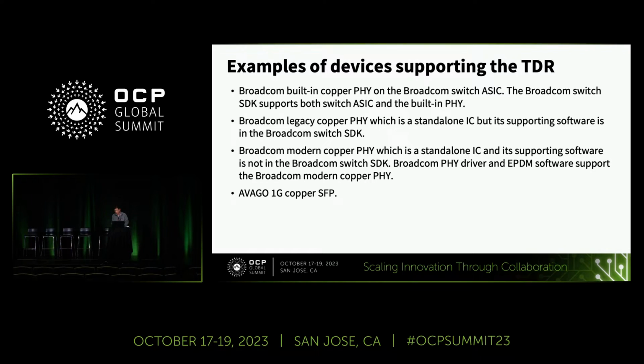I believe many vendors support the TDR function on the PHY, but we only implemented it on the following four devices with SAI, PAI, and SONiC. The first one is a built-in PHY. On the switch ASIC, the switch SDK supports both the switch and the built-in PHY.